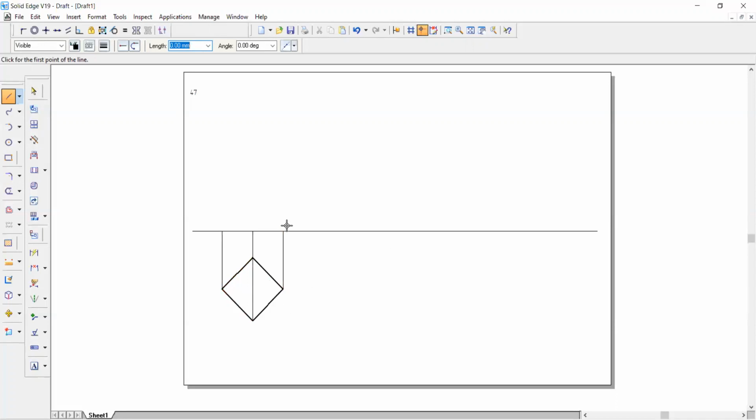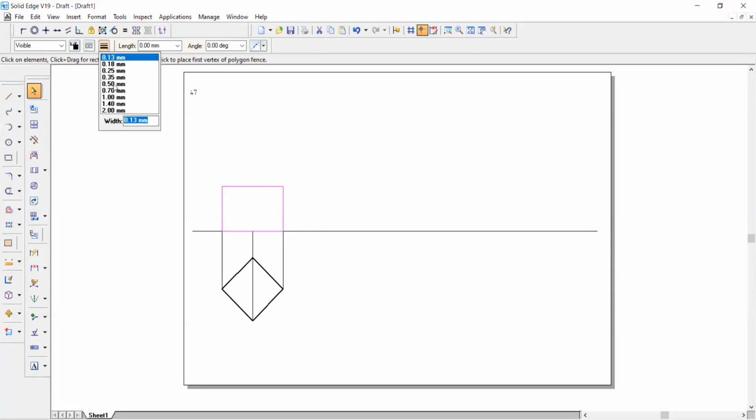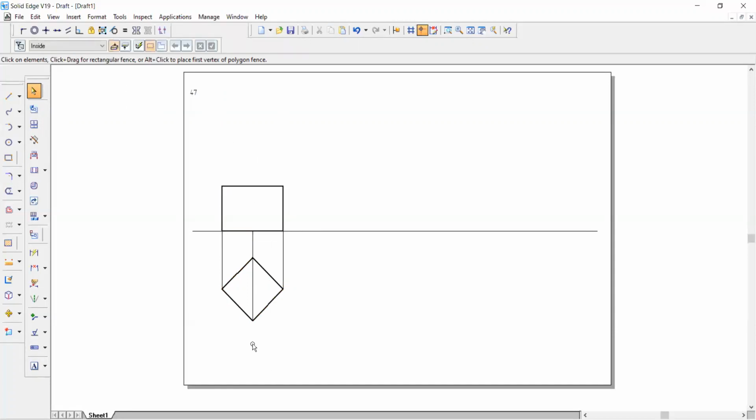The axis height is also 30 here. So what you can do is go for a rectangle, select this end, select this end, then give the height as 30. Make sure that you are entering the value in this particular column, 30, press enter. There is a rectangle placed here right now. Change it to 0.5 thick, and since you are seeing this in the front view, this particular edge will be visible, so you have to draw this line here, which will also be 0.5 thick.